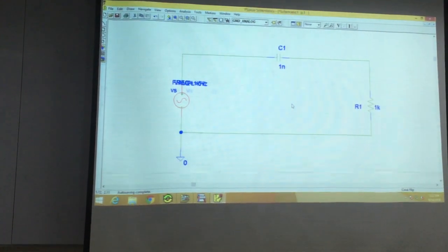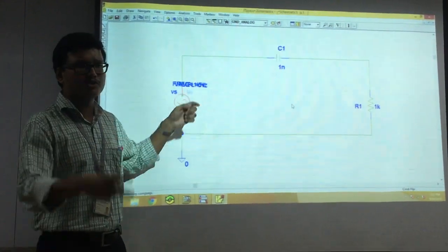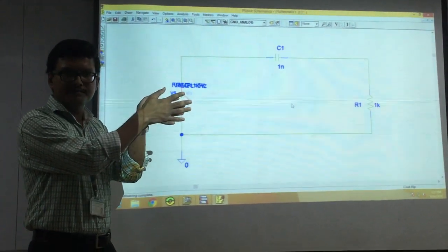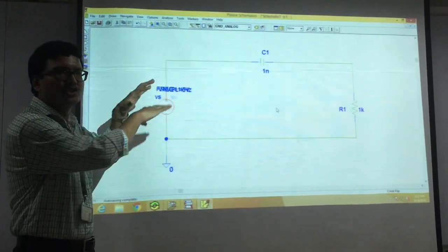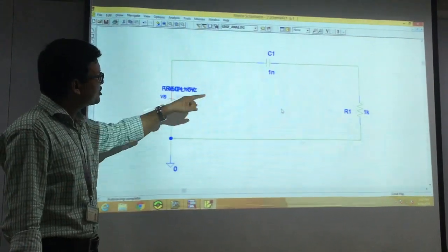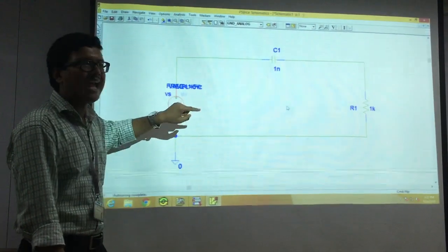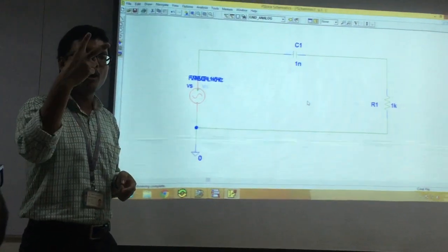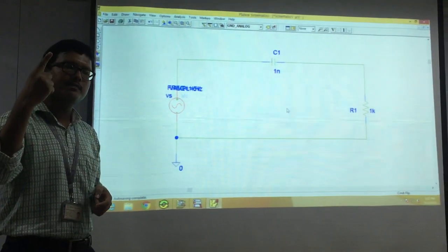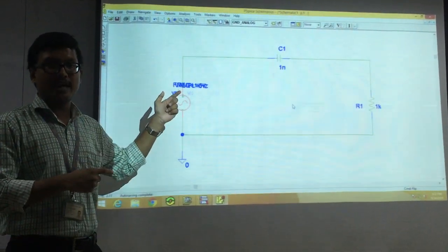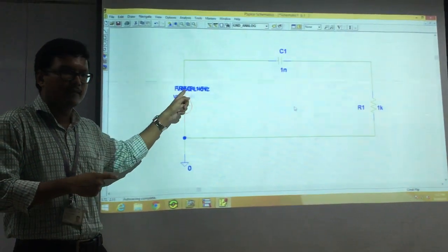But another problem just appeared. Something appeared over here, that means those two properties, but one on top of the other, overlapping, okay. So you need to separate them, okay? How do you do that? You just take your mouse pointer here and click on that. Only one item is going to be selected, not both, one item. Which one is going to be selected? The one that you made available at first. That means VAMPL is going to be selected at first.